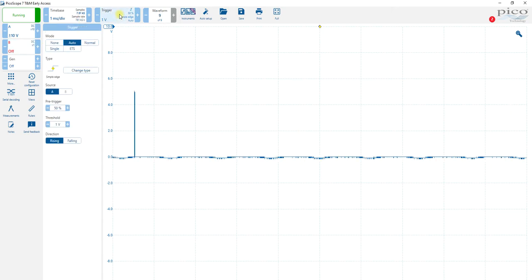And I find this part a little bit annoying that I've set my trigger to 1 volt, but it always sits at the top initially. So I can drag it down if I want, and at least it does trigger on that information. But be careful of that. It doesn't start off with the value shown in the screen. So now that at least I have some trigger, I'm going to change the time base so I can read that a little bit better.